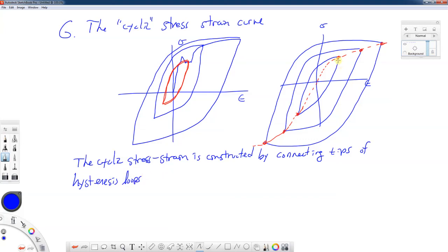And when we do cyclic loading, we could have a stable material, we could have transient material response. We have to decide which hysteresis loop to use, because these can be a little different. Even though we're repeatedly cycling it at the same strain level or the same stress level each time, they can change a little bit. So often people use the half-life values.